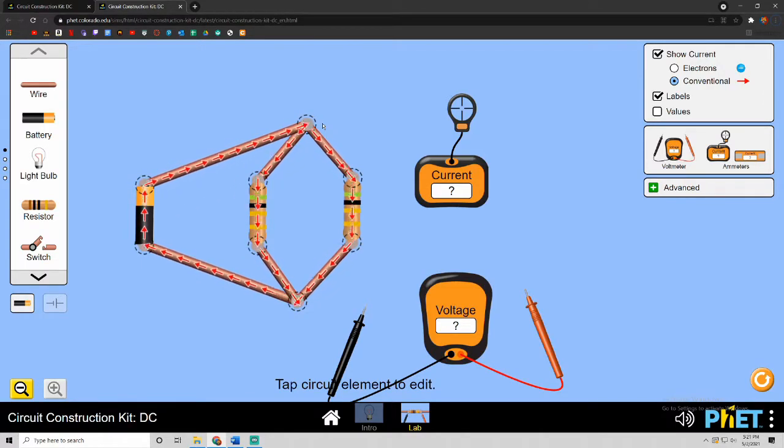We see in this circuit there is the same 10-volt battery but now two 5 ohm resistors each in their own branch. Since voltage still needs to drop to zero in this circuit, the voltage drop across both resistors is 10 volts, which can be shown with the voltmeter.